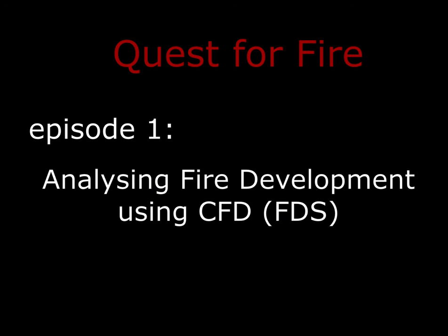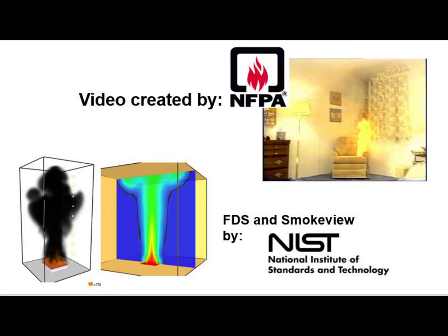In this first video, we will be analyzing the basics of fire development. We will be using an old but very good fire safety training video and the modern tool of Computational Fluid Dynamics. The video we will be analyzing was produced by the National Fire Protection Association, NFPA, and the CFD program is FDS, developed by NIST, the National Institute of Standards and Technology.